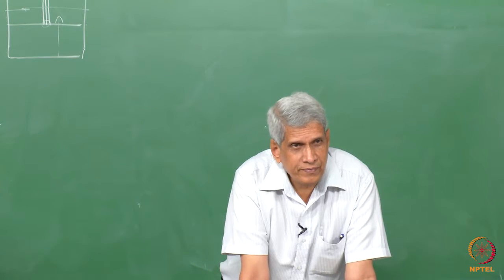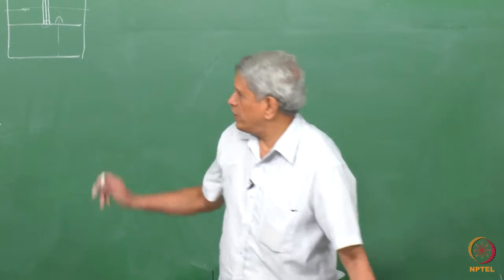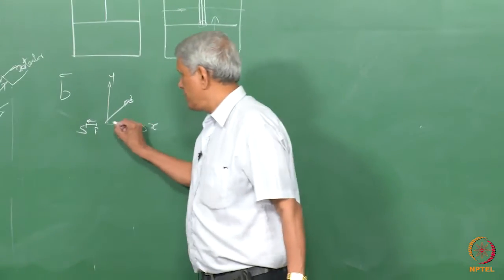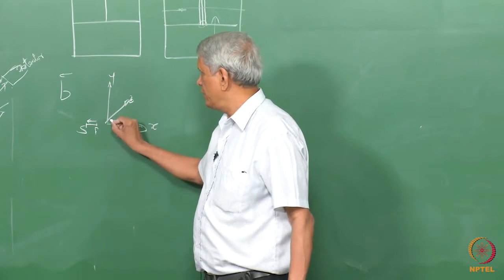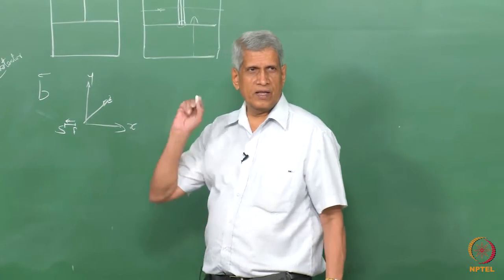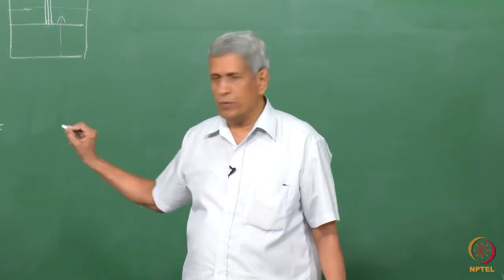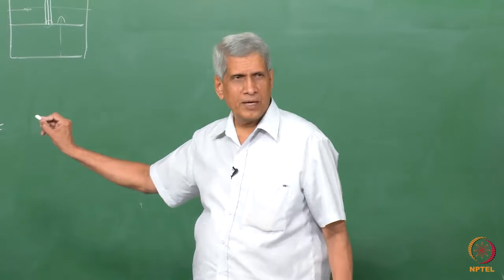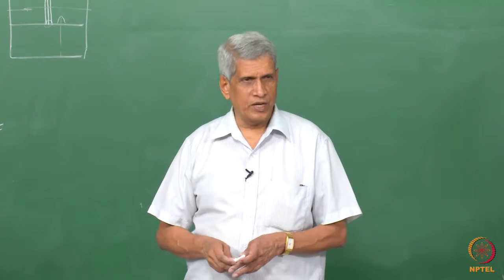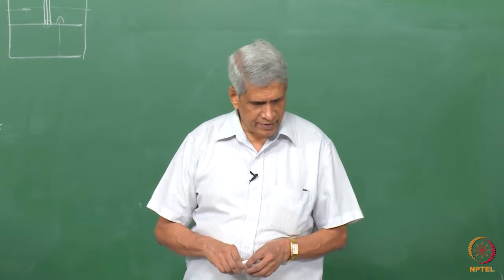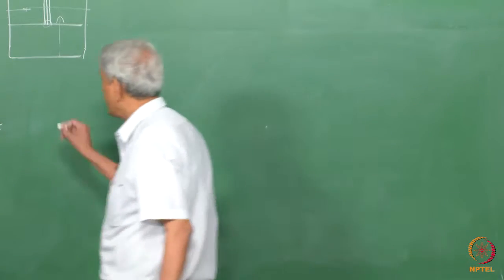So what is important is first the coordinate system. X is this one, Y is this one, and Z is going into the paper, or into the board, which is the line sense of the dislocation. Then the Burgers vector b will be defined in this way. This is called the finish to start